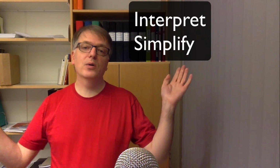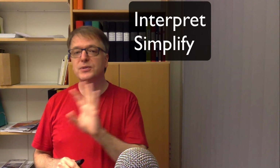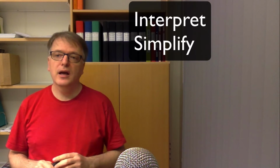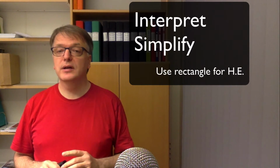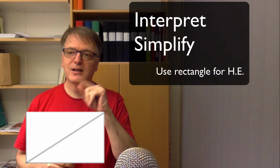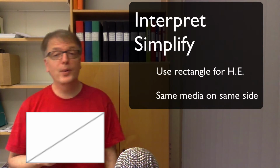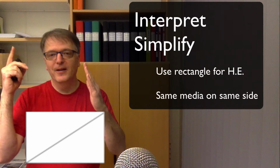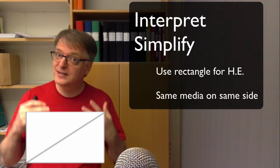So you should interpret a process diagram, and you should make a simplified overview without all these regulators and stuff. Just a few simple things. And when you draw a heat exchanger there, you must use this simplified symbol, the rectangle with the diagonal in it, and make sure that you draw the flows appropriately. So flows on the same side of the diagonal are the same medium.